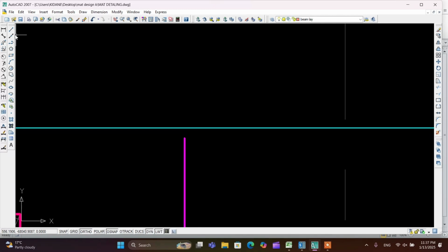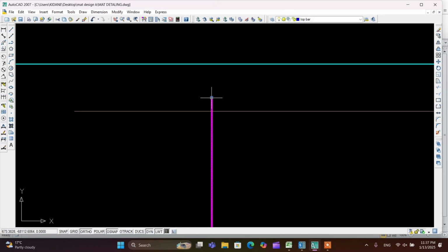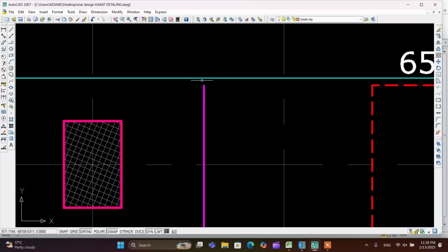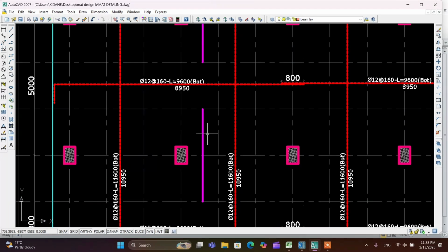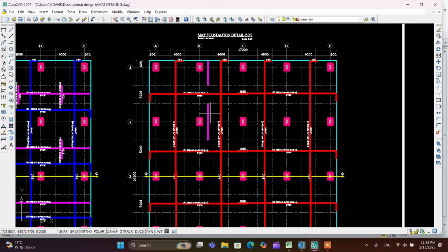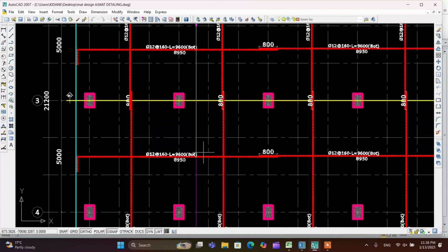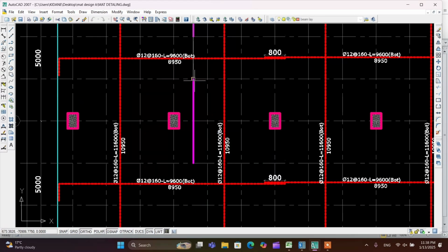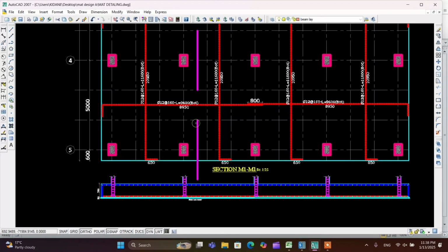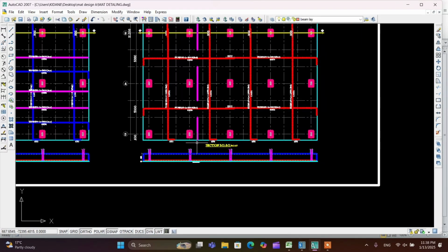You can calculate or you can minimize your concrete cover. So for our reinforcement detail, you can measure all the detail and you have to use a diameter of 10 at 200 millimeter spacing. That is the minimum spacing. So all the additional reinforcement detail around the column for the bottom reinforcement looks like this.